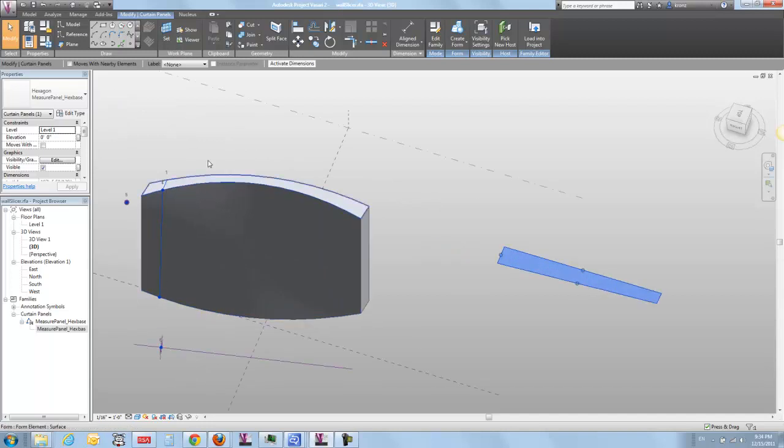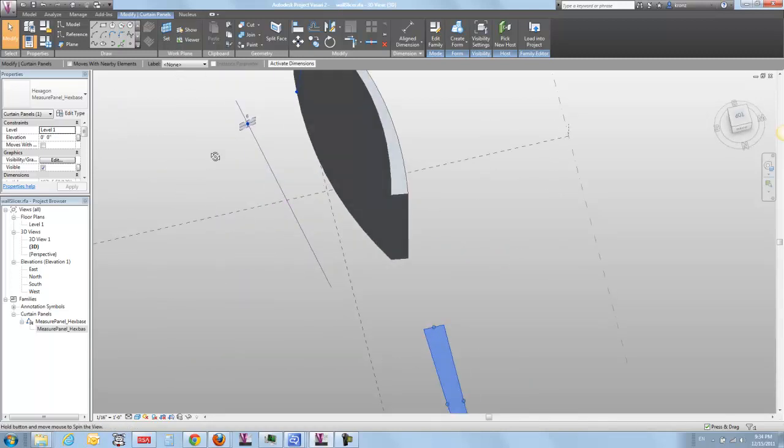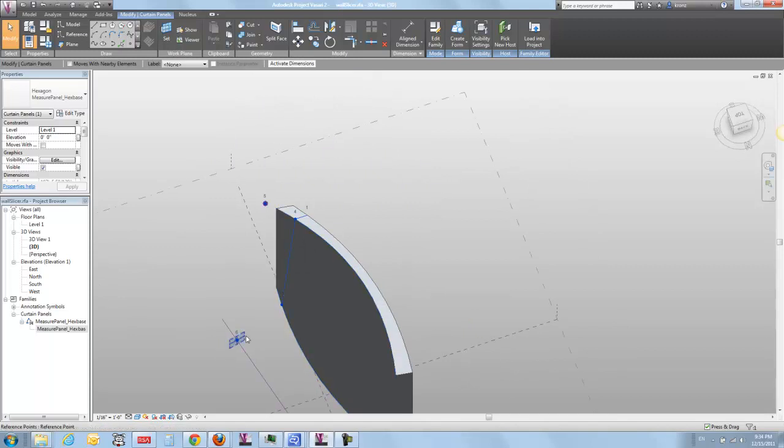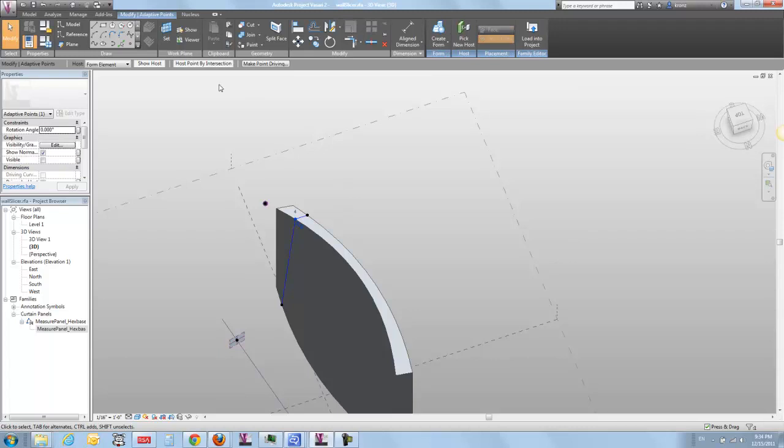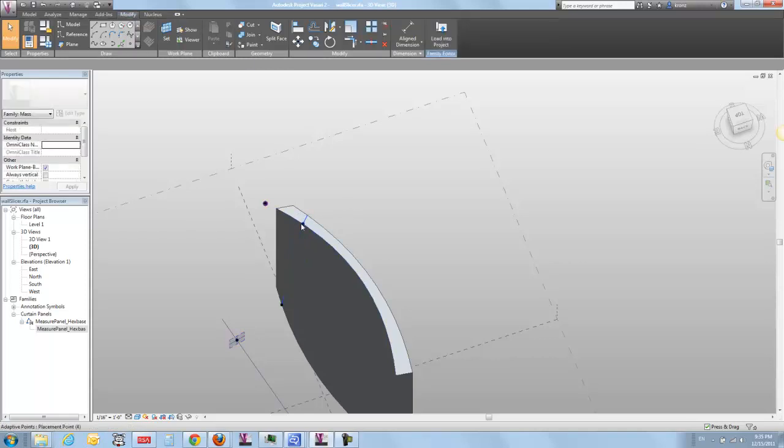Now, one problem is that right now these guys are not all planar, they're not a planar slice. I just sort of slapped them down. So what I need to do is get them to all line up, and that's what I'm going to use this work plane for. So I'm going to select point 4, and I'm going to host it by the intersection with this plane. Bam. Like that. And you see it just lined up.